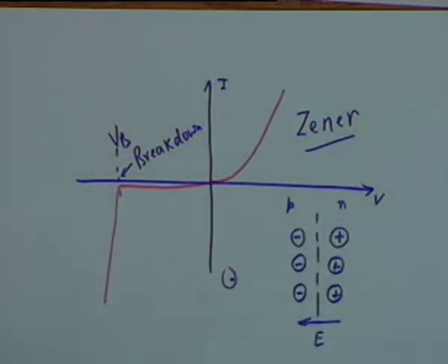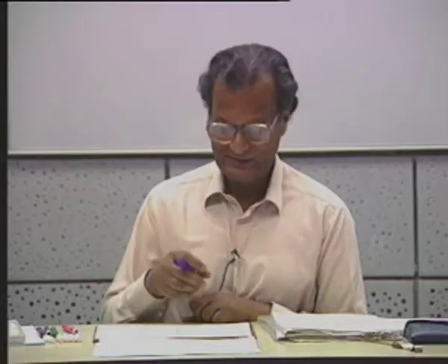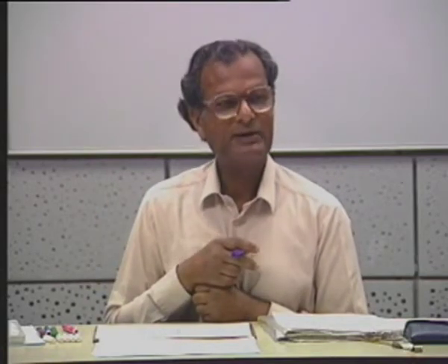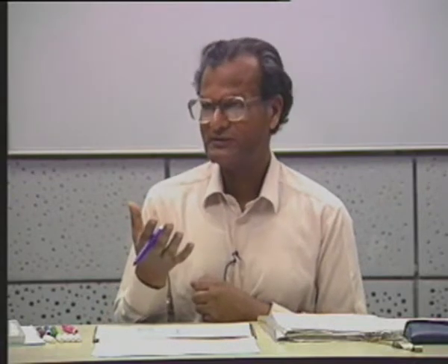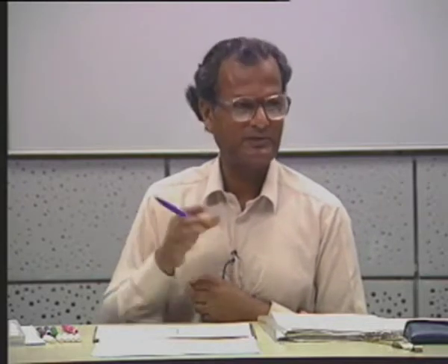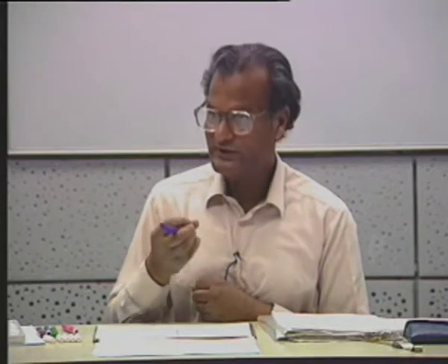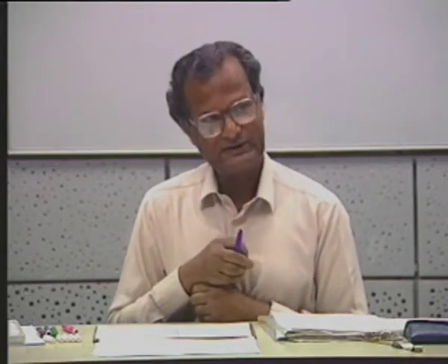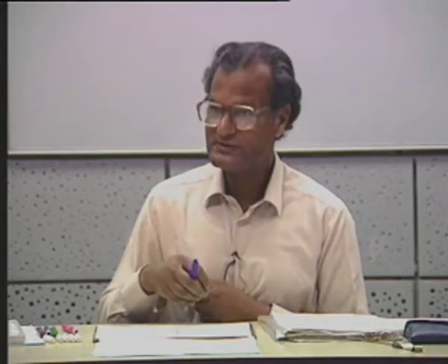It can be precisely controlled, and you can make a Zener diode with almost any breakdown voltage. One point must be remembered: as soon as a breakdown occurs, the current increases drastically. Current multiplied by voltage is the power dissipation. So long as the power is within the dissipative capability of the diode, the process is reversible.